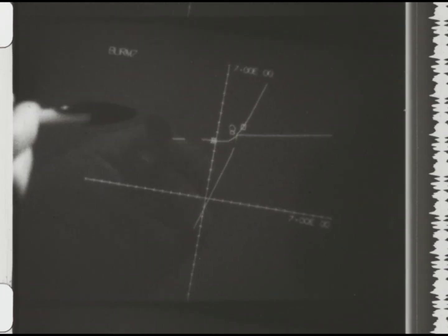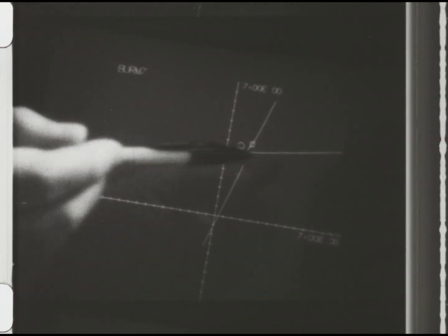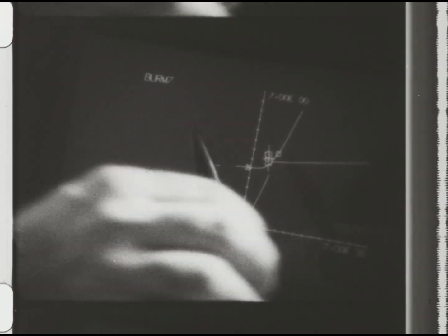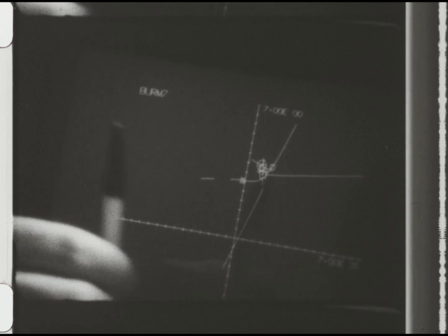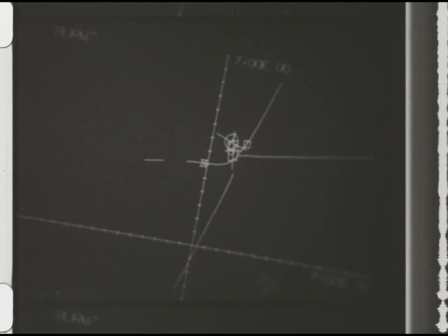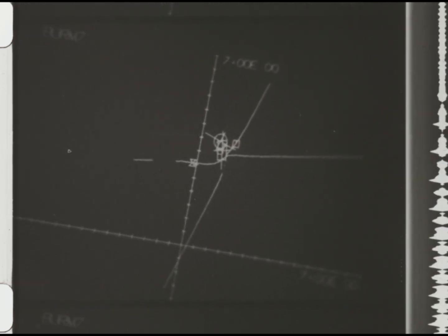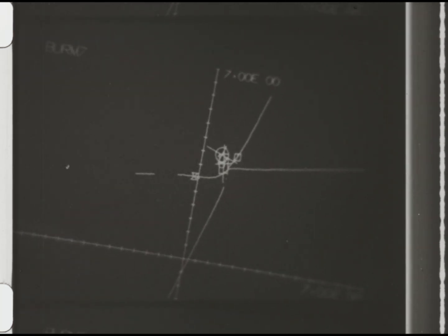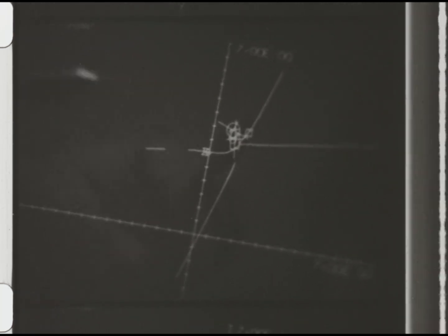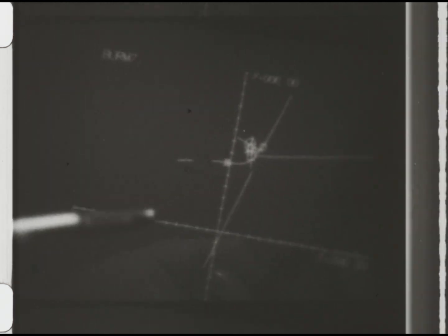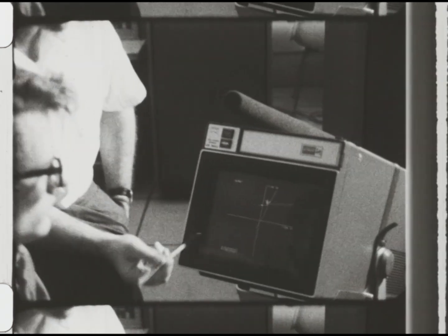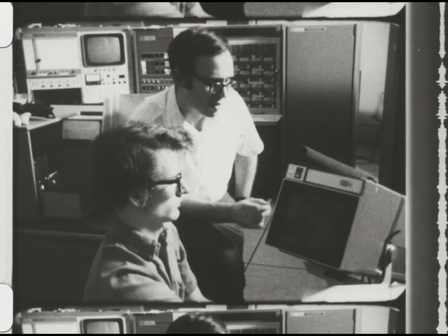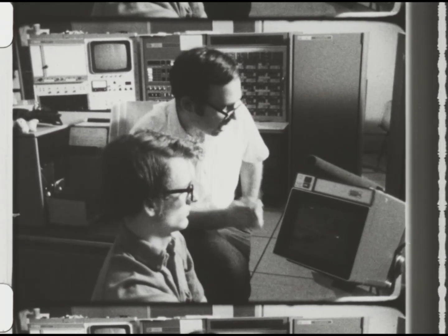These are design curves or synthesis curves, and this curve represents points which, for those 4 design positions, have the property of falling on a circle in each of the 4 positions. The other curve represents the centers of these circle points. And there are 2 symbols in the center here which represent possible sliders for a slider crank mechanism which would be capable of also guiding the body through those 4 specified design positions.